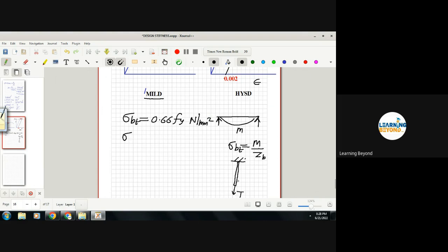Here it is an axial tension stress, so you take 0.6 Fy. If you are designing a purely axial member, such as axial tension in trusses, rods or suspended cables, you can take this permissible value.